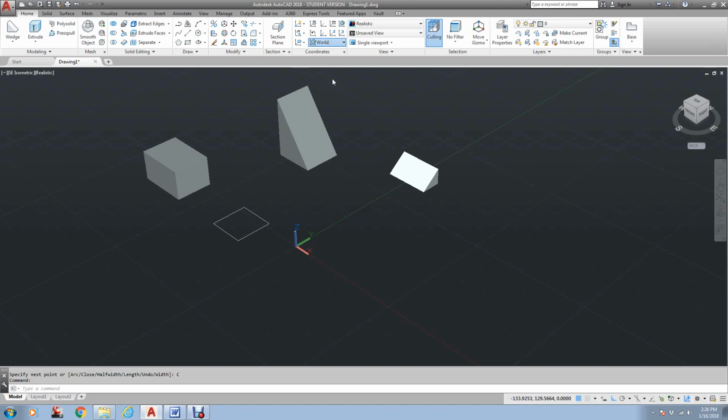Now I'm going to go to the left, and let's imagine that that's the wall to your left, and I'm going to do another polyline, and I'm going to start it right here at this end point, and I'm going to go up 20, go over 20, and then come down 20. Okay, now I'm going to switch to the front plane, which is now, this was the left wall. Now think of this as being the right wall.